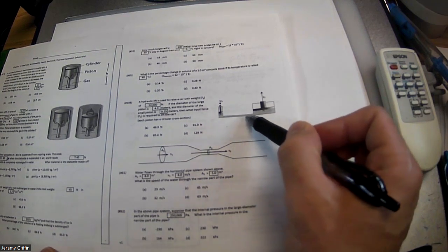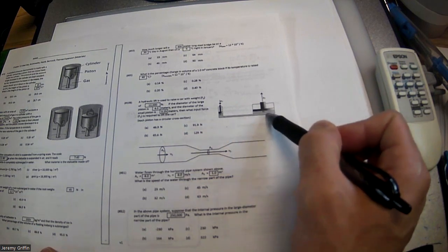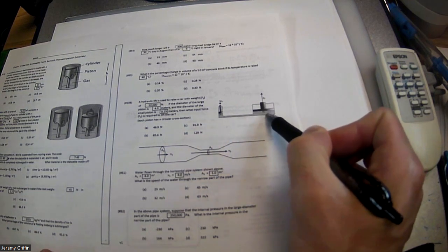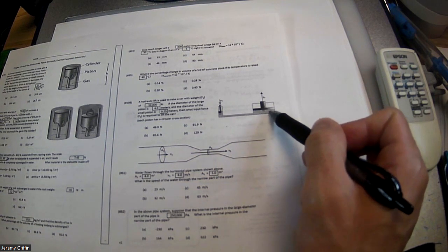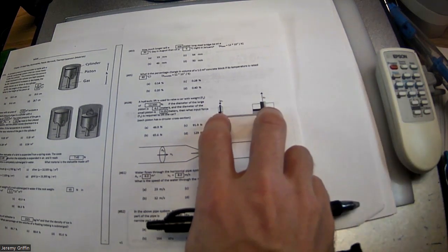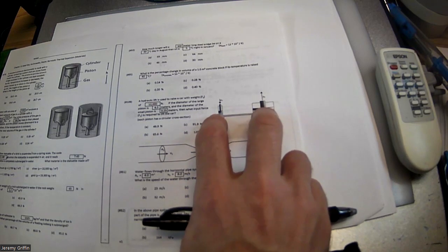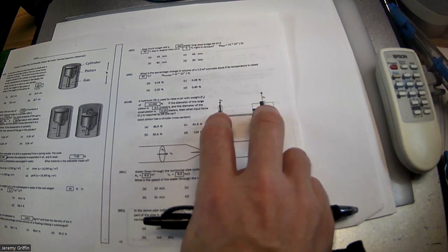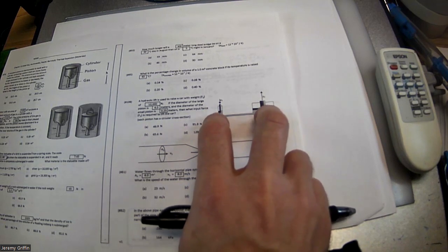Pascal's principle says that the pressure in this fluid down here is transmitted undiminished. And if it's a liquid, maybe it's a little bit more pressure on the bottom than the top, but it's equal pressure at equal elevations. Now, there's some pressure pushing up on the small piston, and some pressure pushing up on this large piston. And it has to be the same pressure, especially at the same elevation. These are slightly different heights, but negligible if it's a highly pressurized fluid. But that's going to result in different forces.